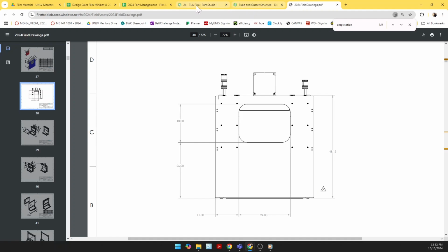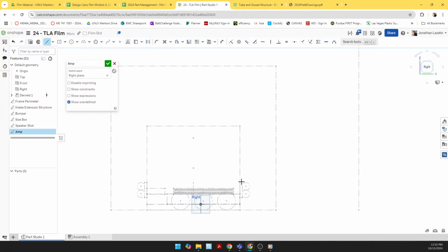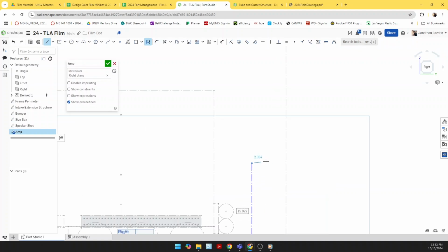And so in my sketch here, line tool, construction, starting at the floor, I'm going to go up. I'm going to create a pocket, and then it's actually a 45-degree slant. This point is going to be vertically constrained to this point since they're on the same face.